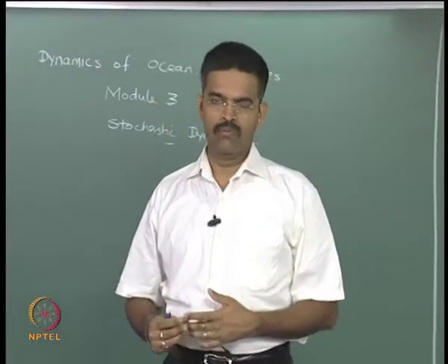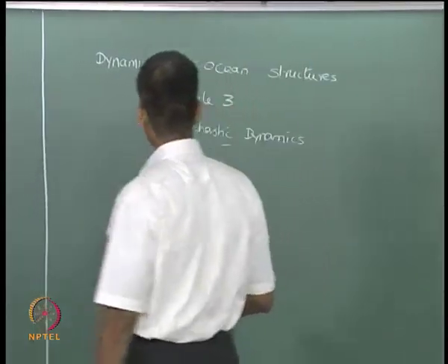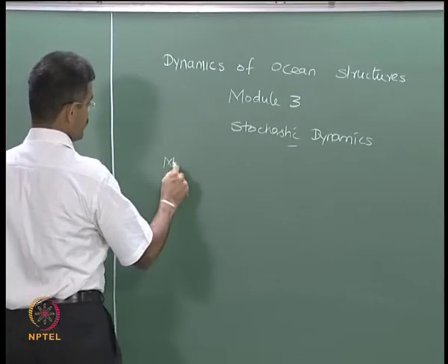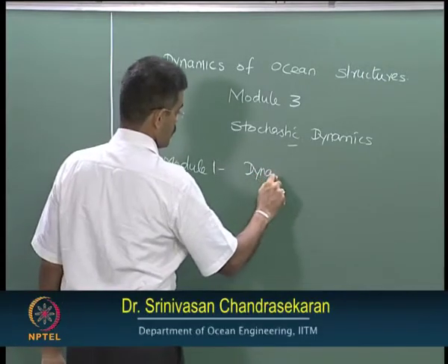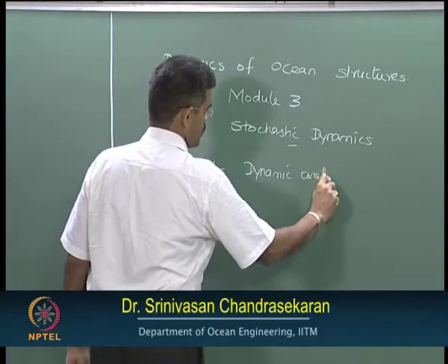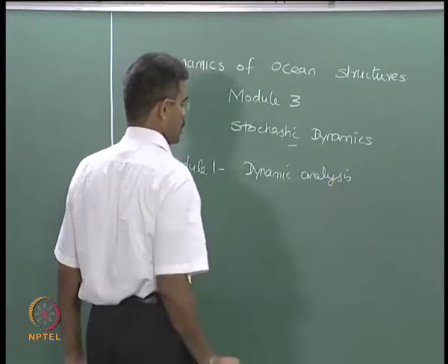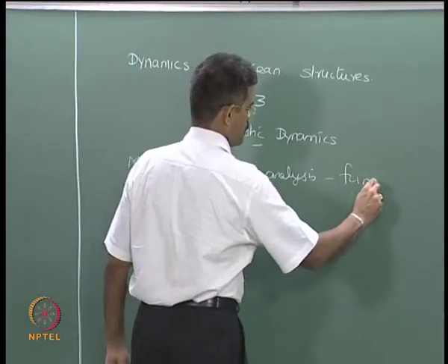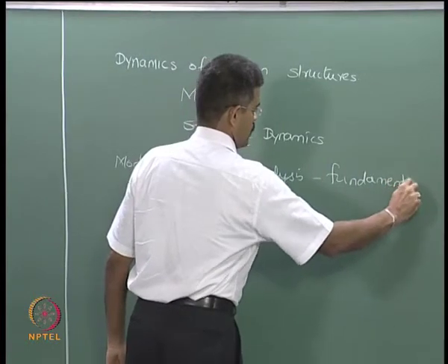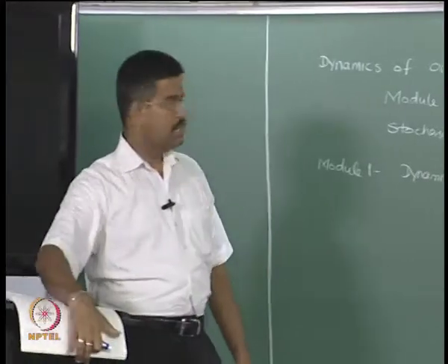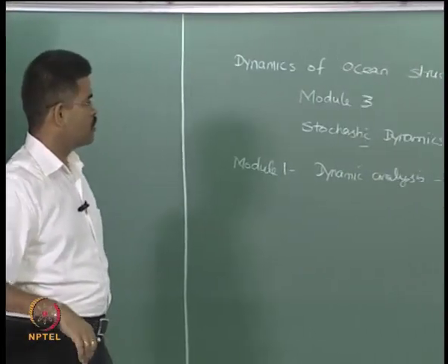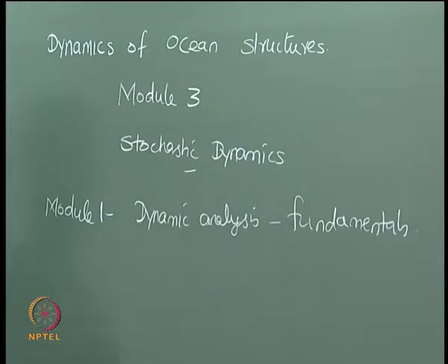So, in the first module we discussed the fundamentals of dynamic analysis. We discussed how to write equations of motion for different single, double and multi degree of freedom systems, how to find the eigenvalues and eigenvectors, or in other words the frequencies and mode shapes, of a given equation of motion.